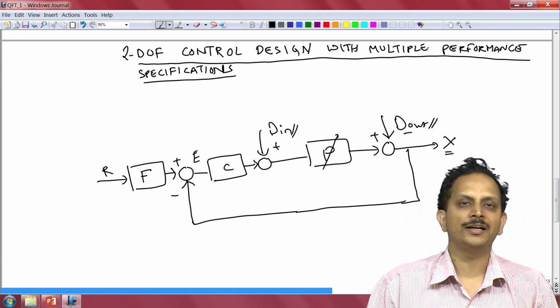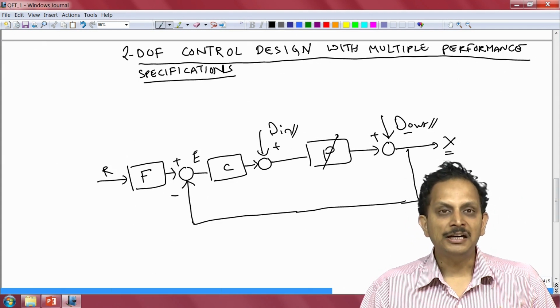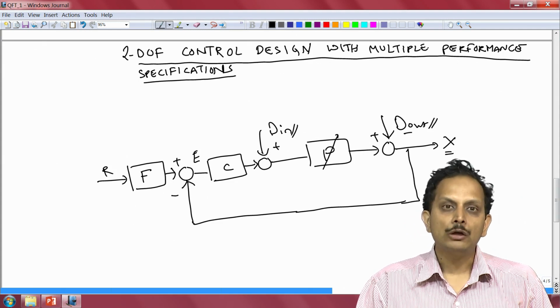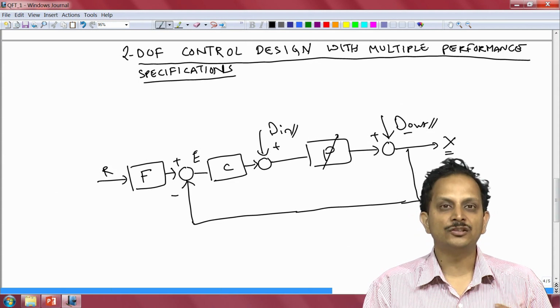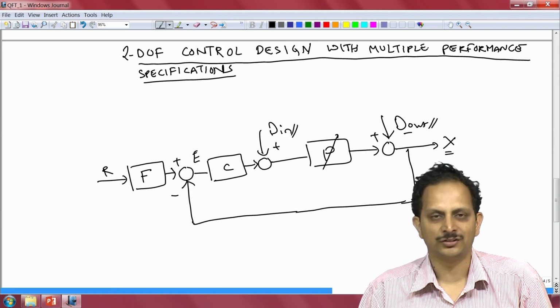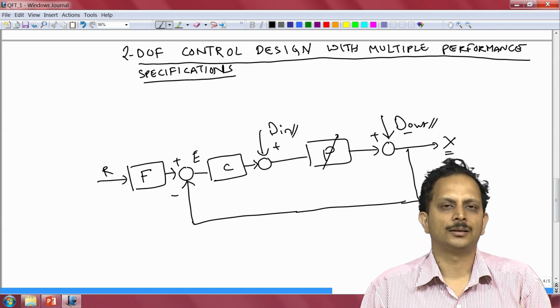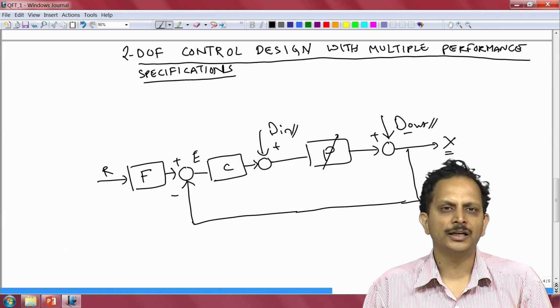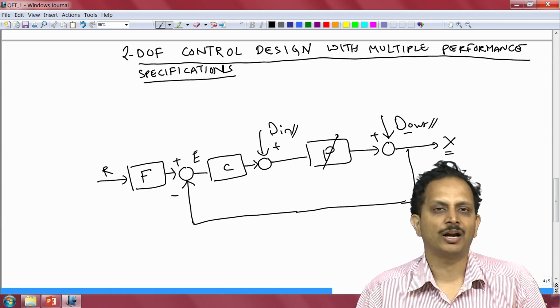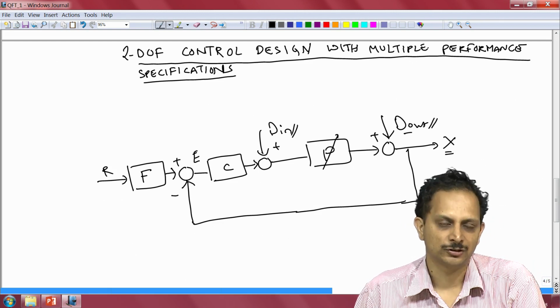But despite this advantage, the clarity that one can get with a Nyquist plot is still not adequate for us to execute our control design in the presence of multiple performance requirements, in terms of multiple disturbance rejections, achieving robustness to plant parameter variations, and also achieving robust tracking of certain reference signals within certain specified ranges.